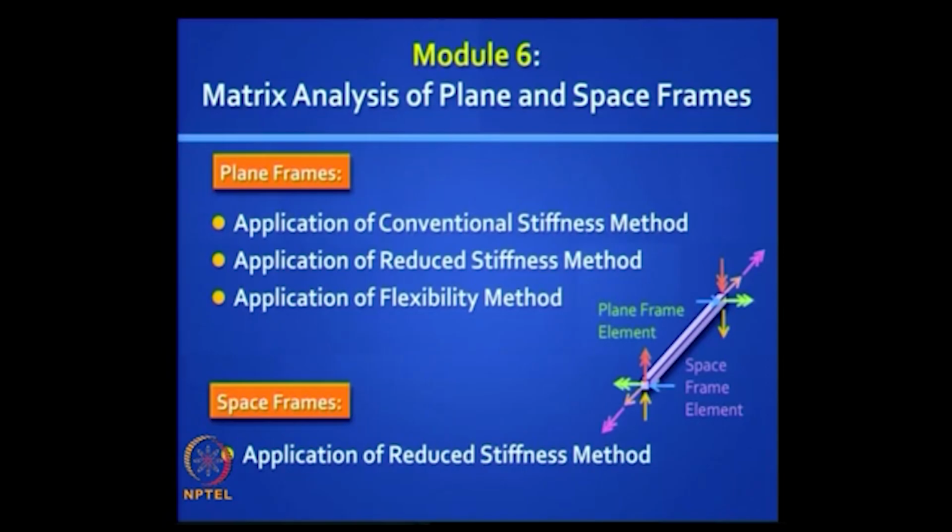All other elements that we have studied are actually special cases of this one element. If you take the stiffness matrix for a space frame element, 12 by 12, and delete rows and columns respectively, you can downgrade it to a plane frame element, to a grid element, to a beam element, to a space truss element, to a plane truss element, and to a 1D axial element.